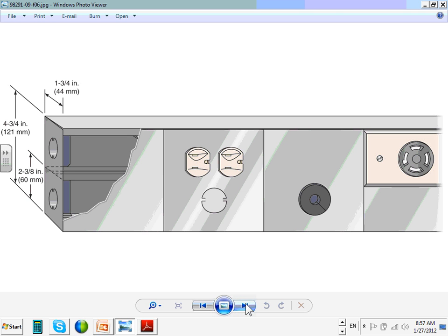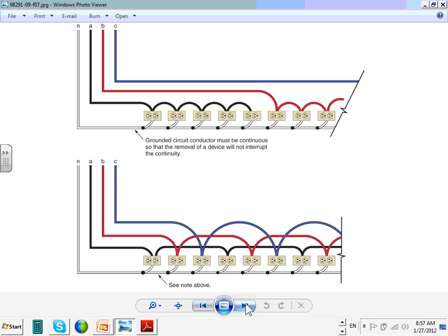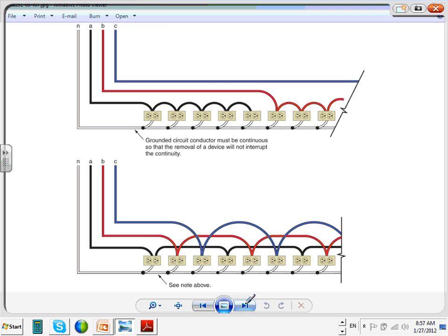Okay, multi-outlet assembly, guys. Two things. They talk about two chambers. You can have one chamber for high voltage, one chamber for low voltage on them. Better explanation: in the multi-outlet assembly, this is my favorite. If you have a 208/120 volt system, and you have a multi-outlet assembly in a commercial building, this is how they wire them. This is typical.